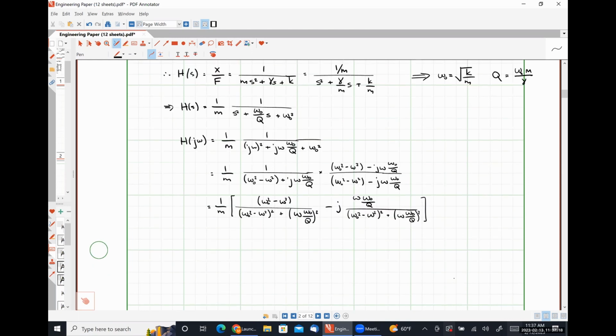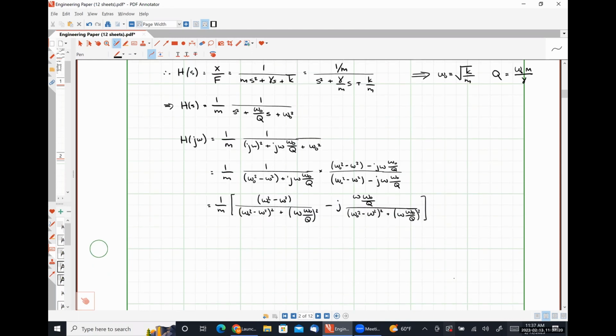So using this transfer function, we don't have to do convolution in the time domain, which, for those of you that have dealt with signals and systems, you don't want to do. We can say that our drive mode displacement as a function of frequency will be our drive mode transfer function as a function of frequency times the drive force as a function of frequency.